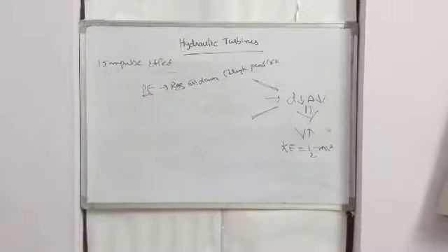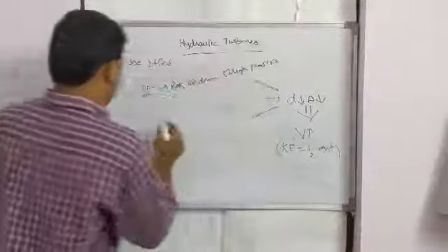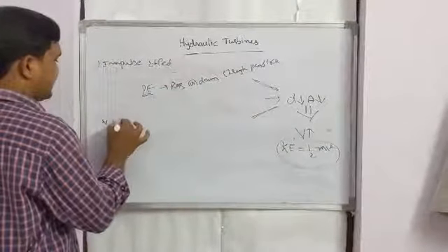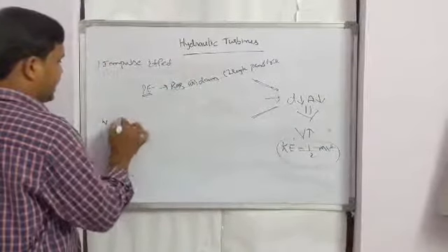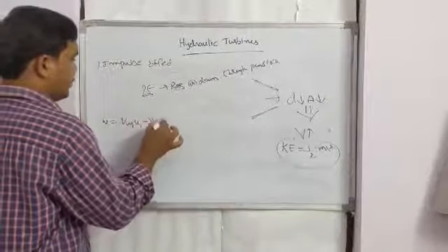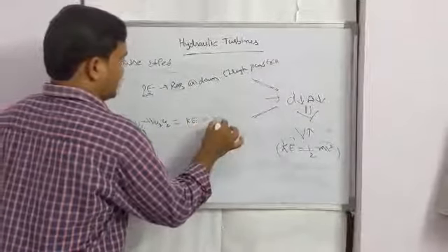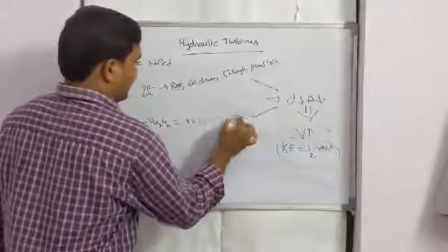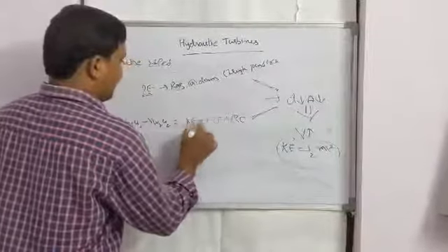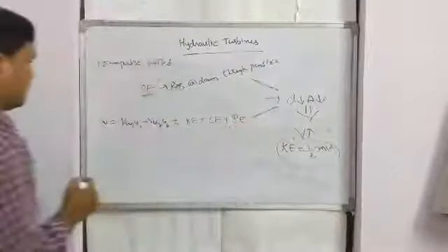So the entire fluid machine works on the pure impulse effect, meaning only kinetic energy takes place. I already told that work done is equal to Vw1 U1 minus Vw2 U2, which is equal to kinetic effect plus centrifugal effect plus reaction effect.